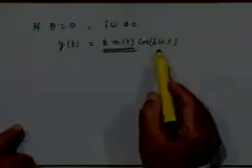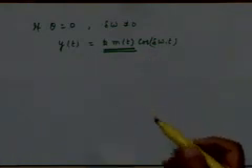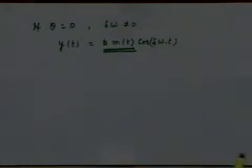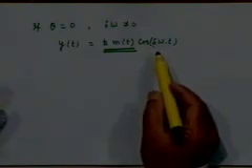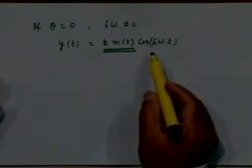But the important case to discuss here is when delta omega is very small, because that is what will practically happen. You will have a local carrier, you will try to adjust its frequency to be as close to that of the incoming carrier, but maybe there is a very small frequency difference left and you are not able to take care of that. This may be of the order of a few hertz, maybe tens of hertz or at the most hundreds of hertz. Typically tens of hertz, if you are using very stable oscillators both at the transmitter as well as at the receiver. The typical frequency difference will not be that high, which will be the case in practice.